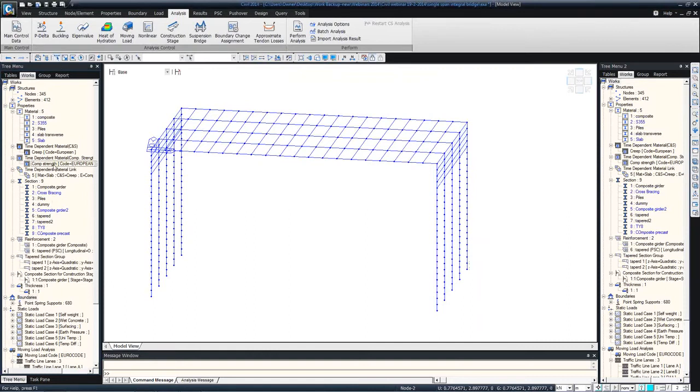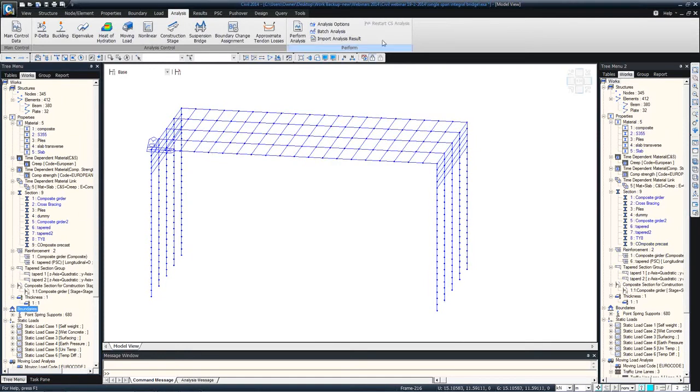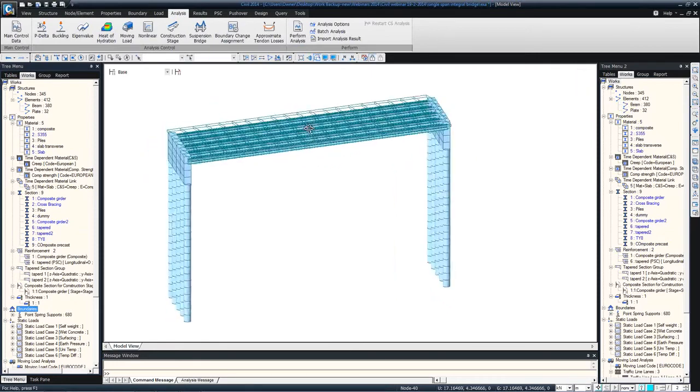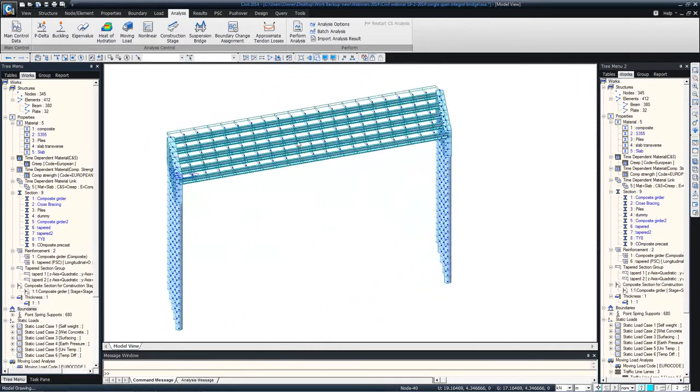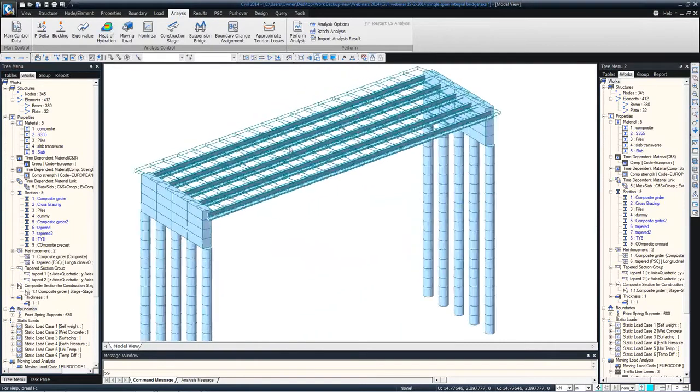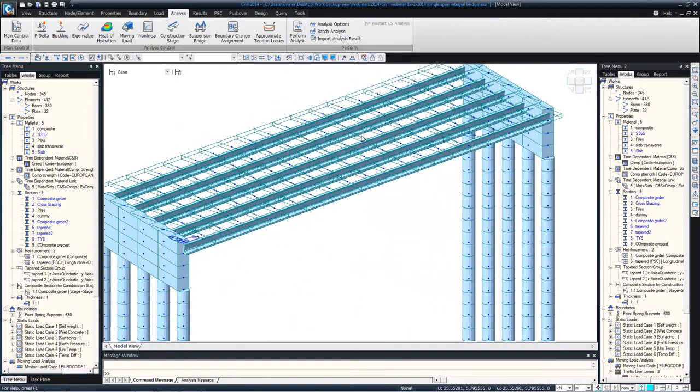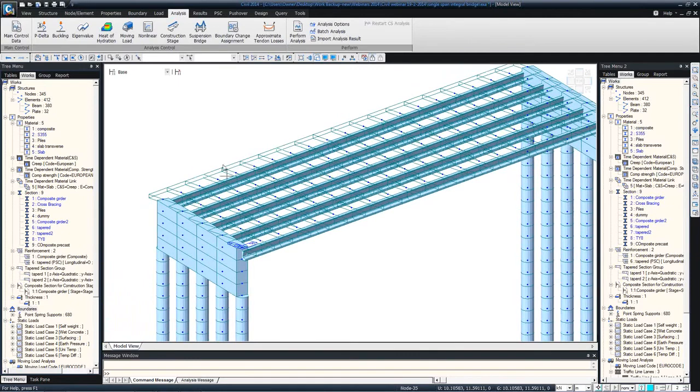Okay, so what I'm going to do is quickly drag and drop the composite precast section. You will see the dimensions are not exactly matching because the section size is too small, but anyways the objective of this exercise is to see how to quickly assign pre-stressed tendons and how the software can do the loss calculation for the tendons, and you can get the ULS effects for dead loads and tendon pre-stress. So I will just activate the precast section.